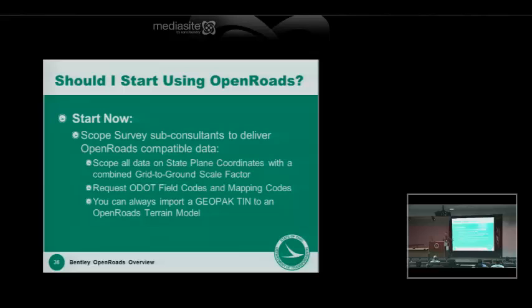Use your GeoPack tools. If you're trying to do something with OpenRoads and it's taking you longer than expected with the learning curve, or you get into a bind, you can always jump back to GeoPack and wrap some things up there.